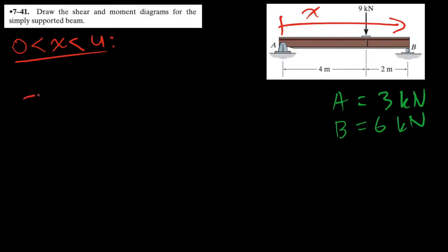And we will sketch this out with a new diagram. The beam is being sectioned here. It's being cut. It's not being cut in real life, but for the purposes of this inspection. So what are the forces applying? Well, we only have force A because this is our x-axis. Let's draw it up like that.